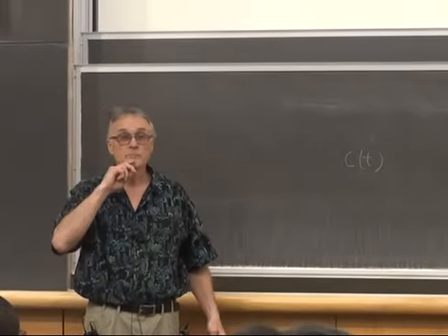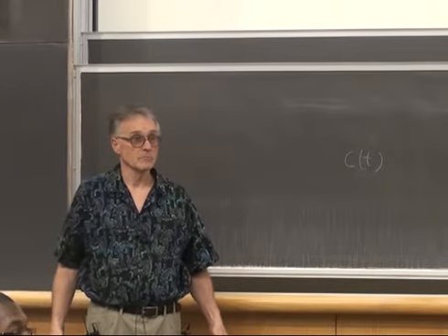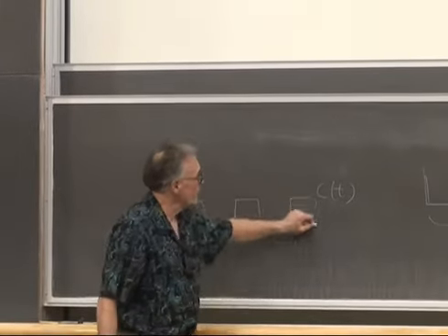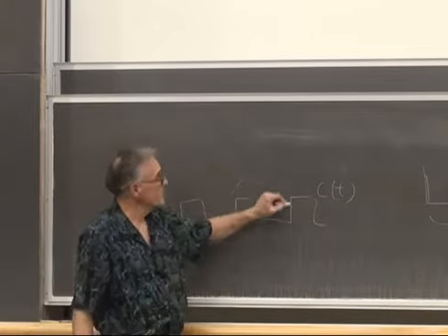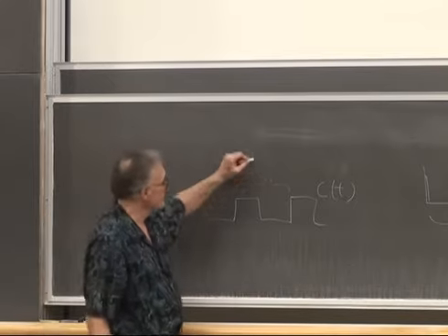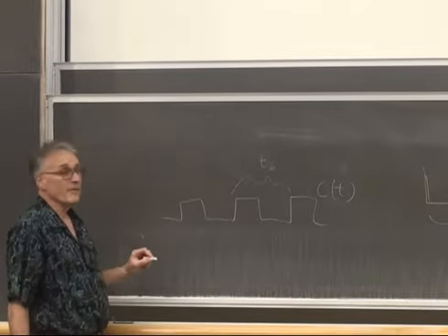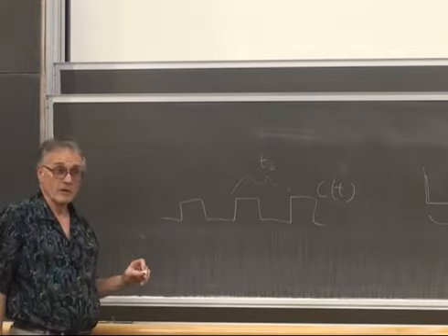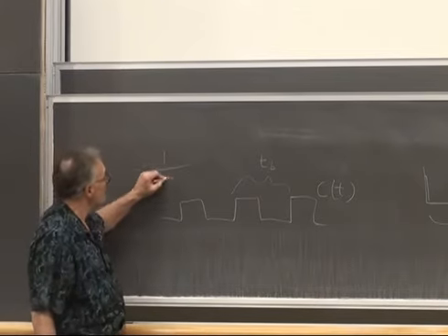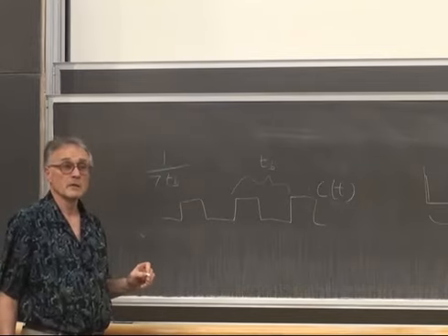How might you convert the infrared output into the actual RPM band? So the infrared output is a square wave, probably 1 pulse per fan blade, right? So you want to get RPM from that? So this is T of 1 blade, right? So 7 times TB is going to be 1 revolution. So 1 over 7 times TB is going to be a speed. Yeah? So you can't do that on the oscilloscope.